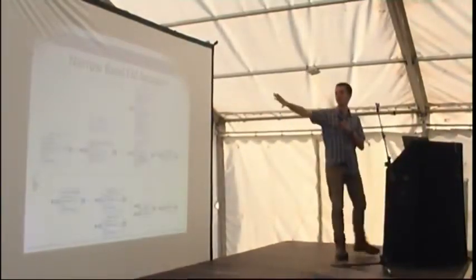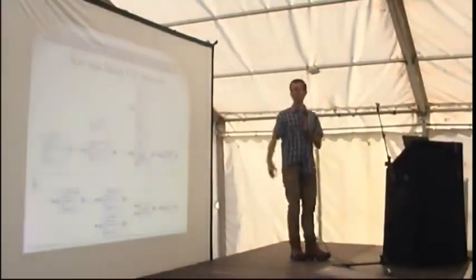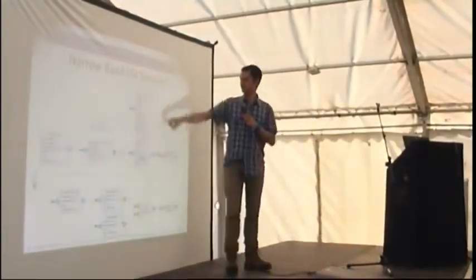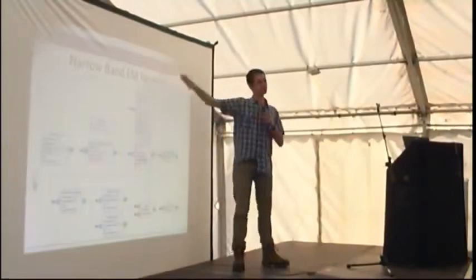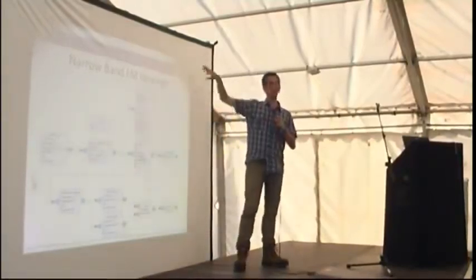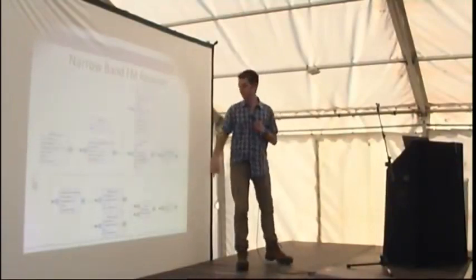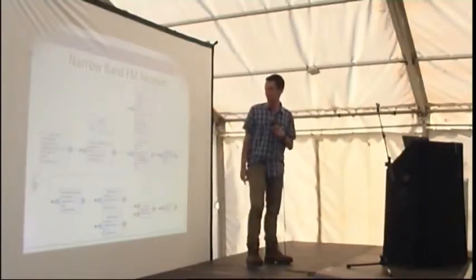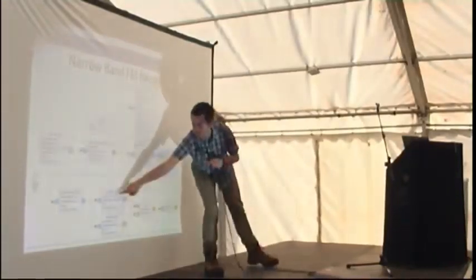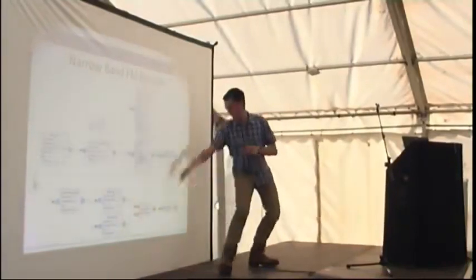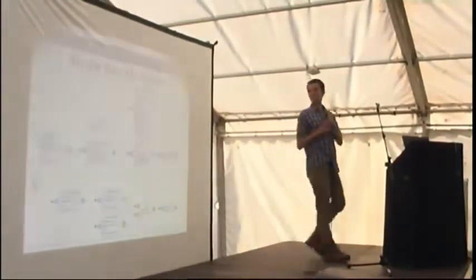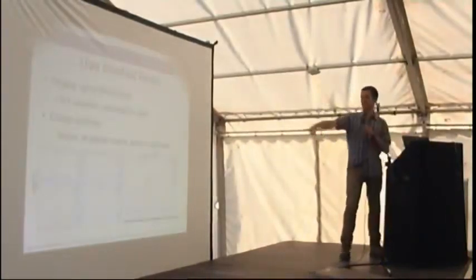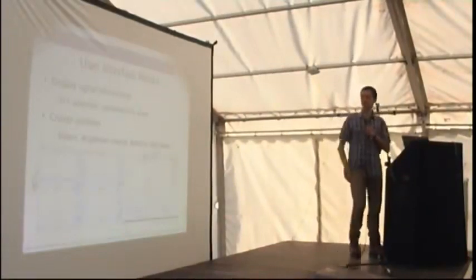So this is what GNU Radio looks like when you download the graphical companion. And you can see we have a signal source coming in, and we filter it, and we look at an FFT, which I think is just the waveform that we were seeing before, showing the intensity over frequency. Low pass filtered again, simple squelch so that we don't hear just shh all the time. Do a narrow band FM receive and output out to the sound card, and you can receive FM radio. And so again, that's what that looks like. And this is the FFT down here, so you just get the nice output, and you're listening to radio.